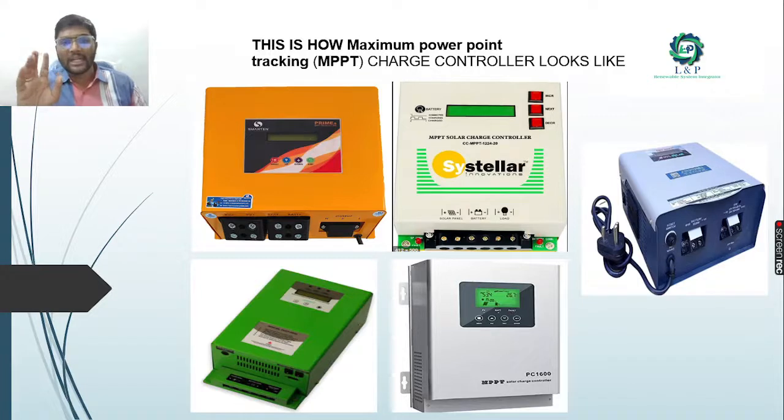Most importantly, for small MPPTs there is no need for any separate power supply, because it takes the supply from the solar panel and from the battery. But when you go for a domestic purpose with a higher current rating, for example a 30 amps, 40 amps or 50 amps MPPT solar charge controller, when the current rating increases, those controllers have a plug point to connect with a normal power supply, because it needs some power for the electronic components to work properly.